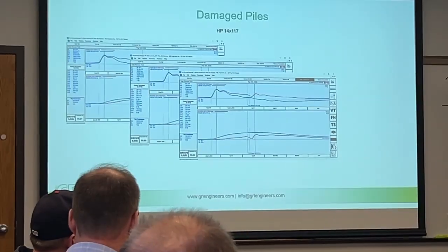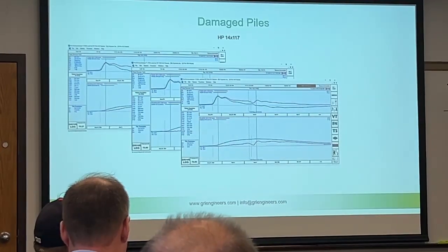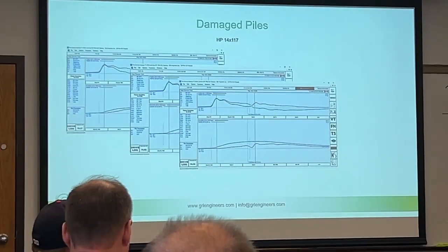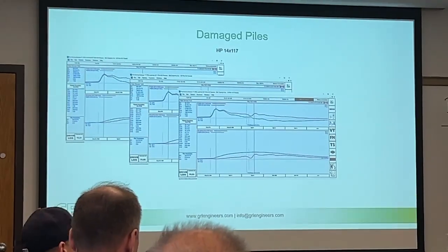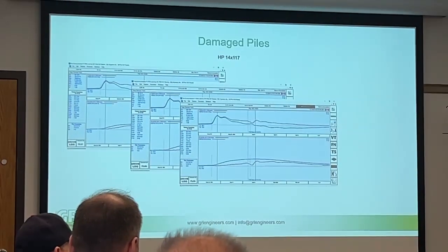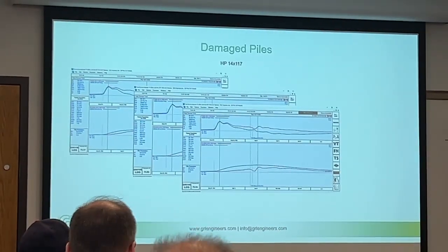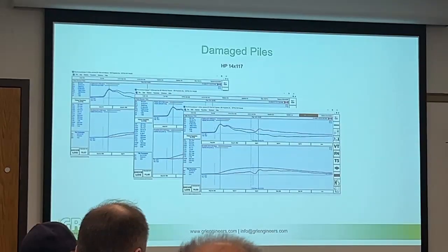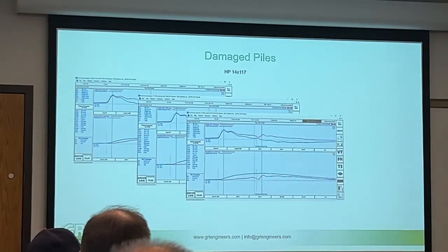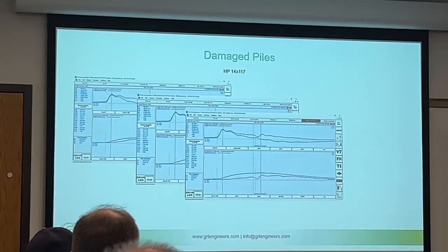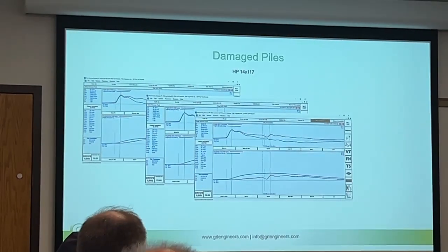So it's hard to get a sense of how much it's changing because we get a number in beta. We are looking at how much that dips down to a peak. And at the toe, things are superimposing upon one another. And so the reflection from the toe is going way down deep. And we expect that, so we don't calculate a beta because it's the end of the pile. And when those two things start to superimpose upon one another, we can't get a good beta number so close to the bottom. How far above the toe does it stop making a beta marker?